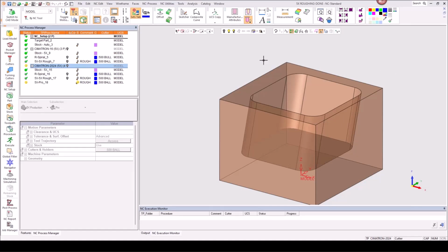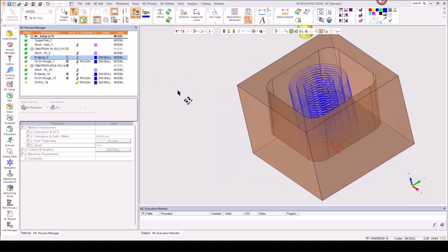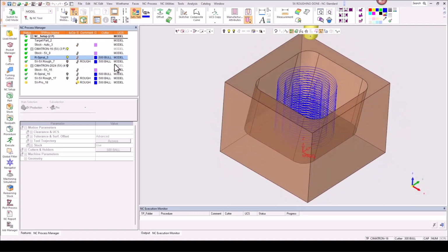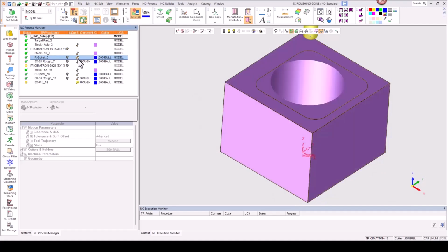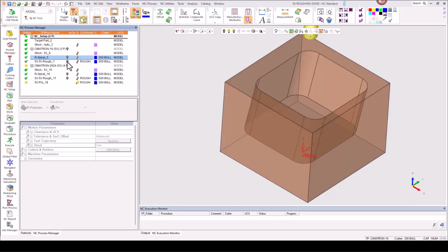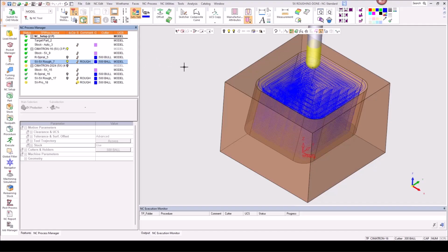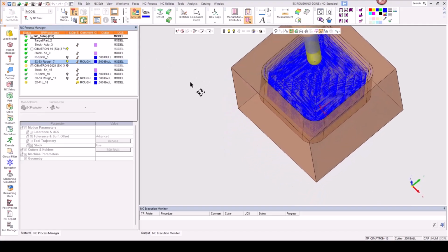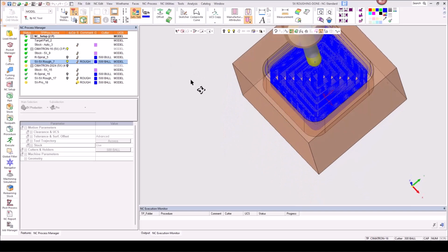All right, the last thing that I wanted to just quick show you guys before we take off is a small change with the use of stock in 5-axis, full 5-axis procedures. So in version 16, had we roughed out a pocket like this, and this is just an example here, guys, but we would have this remaining stock. If we were to try and use the 5-axis rough or a 5-axis pro, the toolpath would look like this. It wouldn't know that there was material gone.